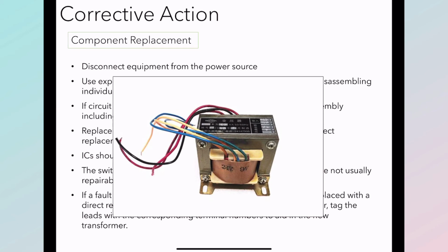We should not try to replace the components which are working fine, so we should leave them there, because if we replace the fine ones also, the procedure of disassembly and reinserting the components may cause damage to the soldering, and also the circuit board itself. It may loosen some connections, and resoldering may cause some issues in the circuit. So if it is working fine, there is absolutely no need to replace the component.